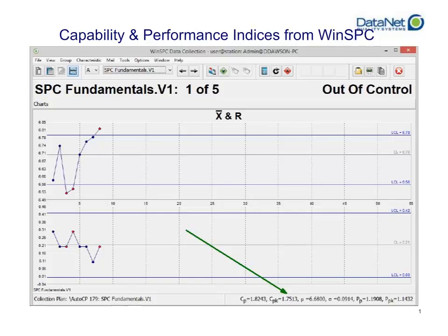It further bears mentioning that even if you have a high CP and CPK, you probably still want to look at your control chart, and you're also going to want to look at your histogram. Because to get a complete view of the story, you really want to put all of these numbers in context. You also want to see how your capability is now versus how it was in the past. You want to be able to run these numbers over time to see if your process is failing or your process is improving.